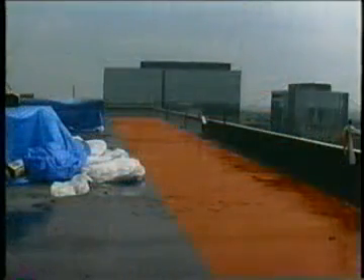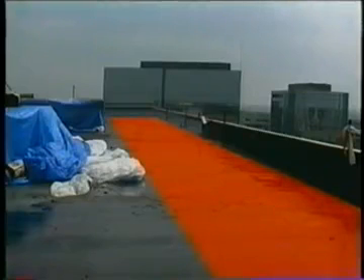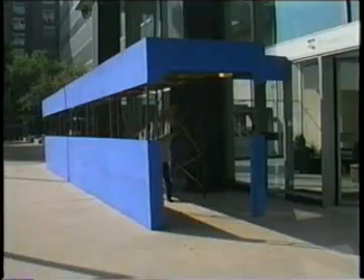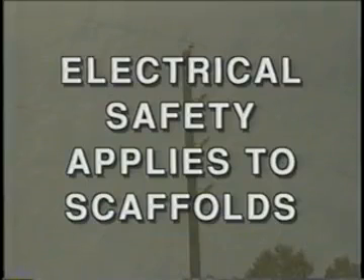Materials shall not be stored within 6 feet of a roof edge or open side unless a guardrail system has been erected at the edge. If guardrails do not provide adequate protection from falling objects, then a canopy should be installed over walkways or work areas. The canopy must be strong enough to prevent falling objects from penetrating it and to prevent its collapse.